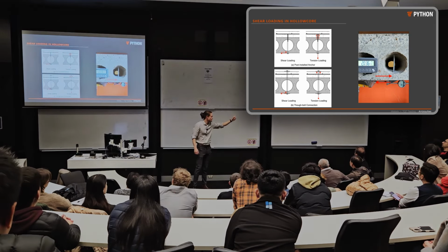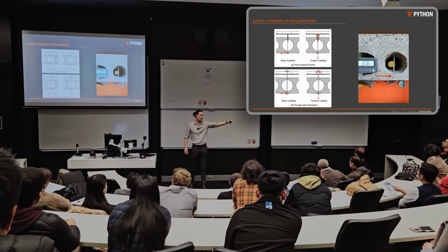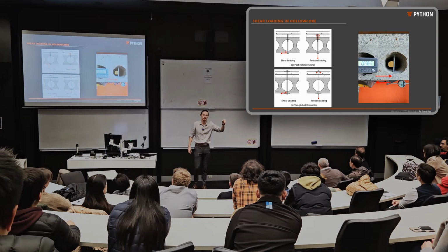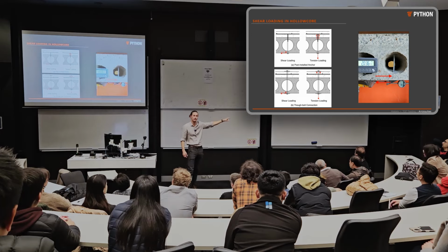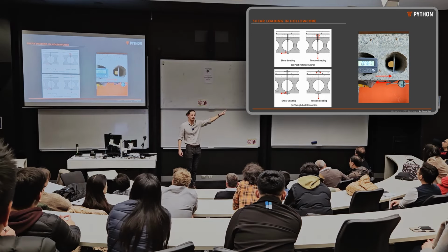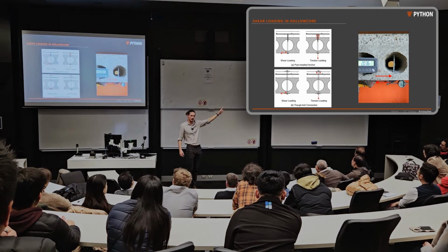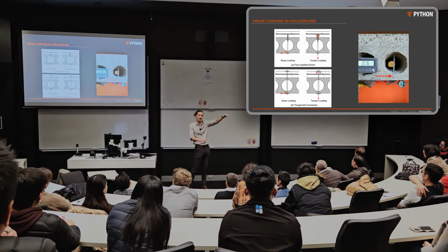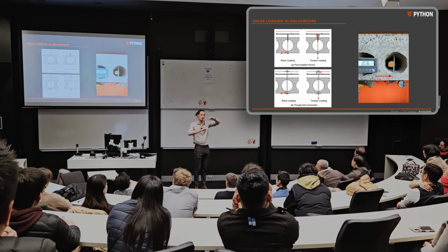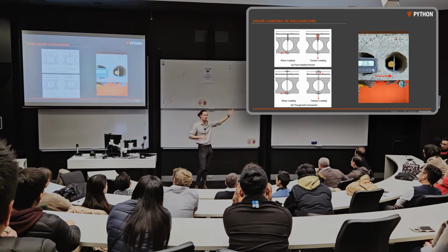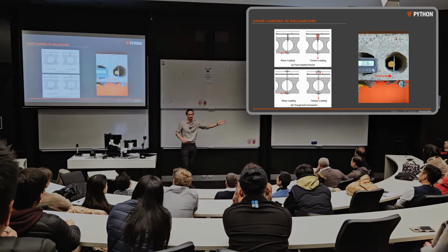If you look at the shear connection, look at the through bolt, we load it in shear underneath the unit. Overwhelmingly, the shear resistance is coming from bearing between the steel shank and the unreinforced concrete underneath the core. The screw anchor, or any anchor really, it doesn't actually have to be a screw anchor, exactly the same mechanism. Okay? C2 capacities for that shear loading of an anchor through a core of a hollow core unit, because you have that offset between the point of resistance, which is a bearing, and the actual post-installed connection, it's just not at all represented by a C2 capacity.